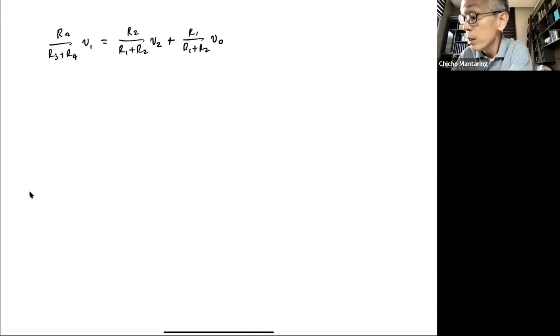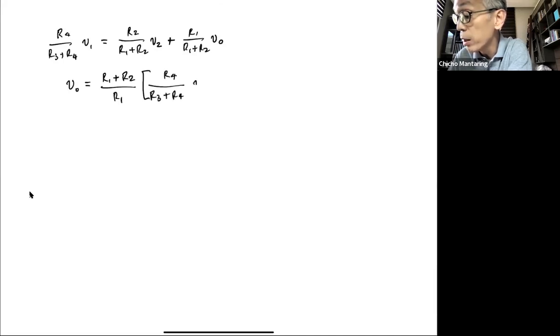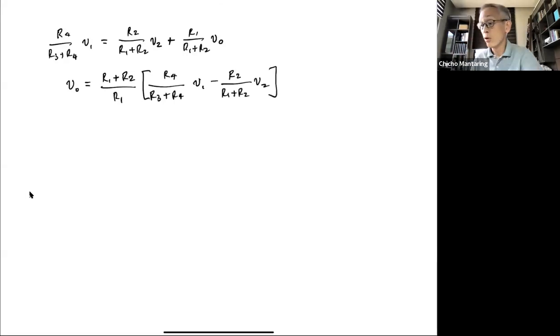Okay. What is V sub O? V sub O will be equal to R1 plus R2 over R1 multiplied by R4 over R3 plus R4 V1 minus R2 over R1 V2.